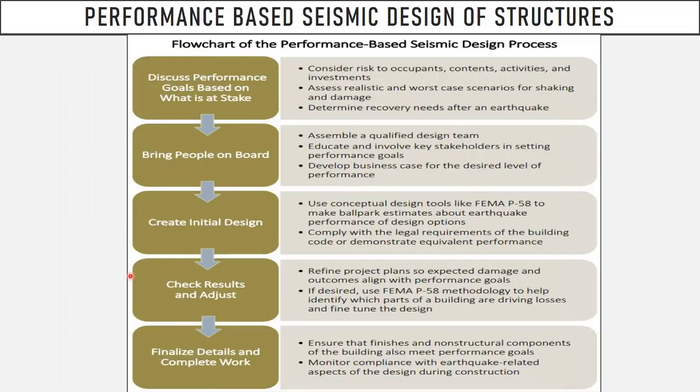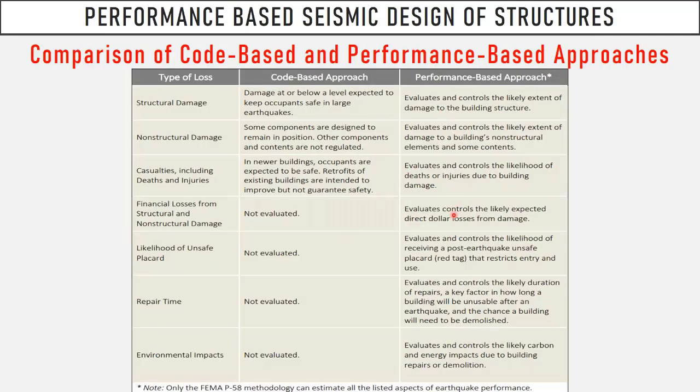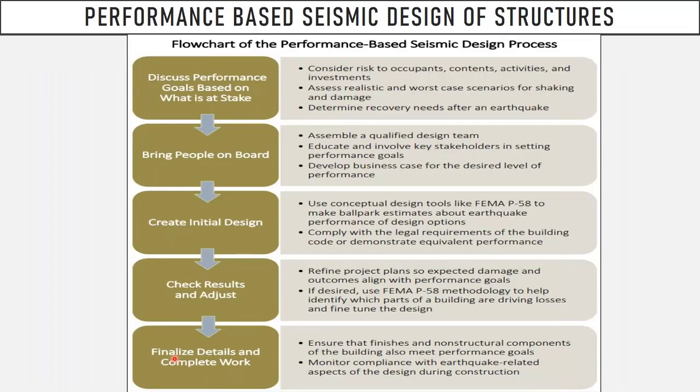And at the end, you should have a kind of quality check. And FEMA P58 provides a kind of guideline, even a tool, on how to quantify these, because there are so many fancy definitions here. What will be the structural damage, non-structural damage, but how do you quantify it? How do you calculate the repair time? How do you calculate the environmental impact of the loss? That document provides you a guideline, both in terms of theoretical base and application. They even provide a kind of tool.